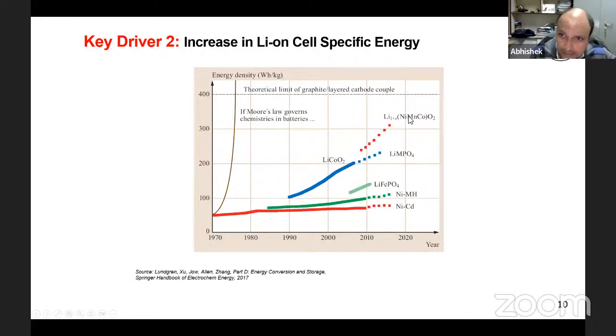And second is, of course, the battery capacity. This is a graph which gives you an idea of how battery technology has been changing, starting from nickel cadmium rechargeable cells, nickel metal hydride, and now lithium polymers and lithium solid state batteries. This has come up by leaps and bounds. Now you can easily buy battery systems which give you 200 watt-hour per kg to 300 watt-hour per kg. Already you can get batteries which give you 250 or so watt-hour per kg, and the world is slowly moving towards 300 watt-hour per kg, but it will take some time. It's not entirely achieved and not readily available.